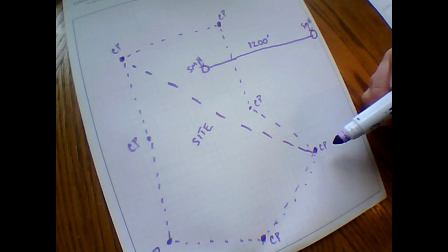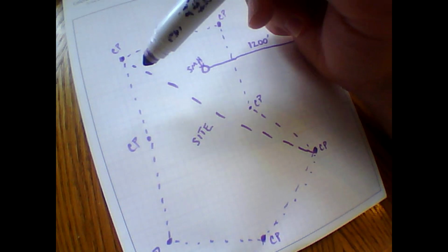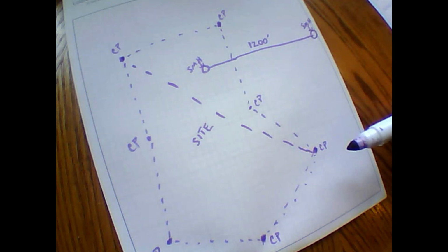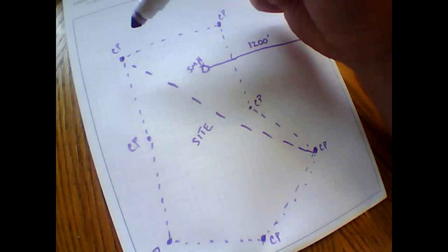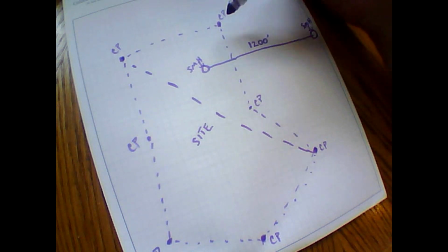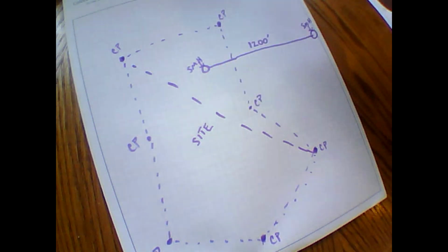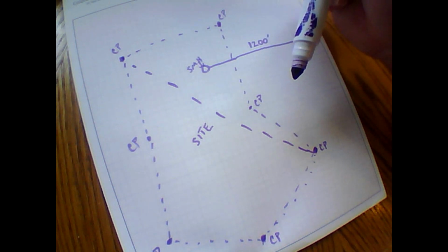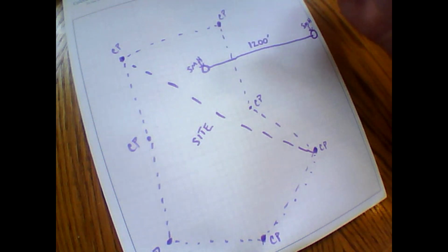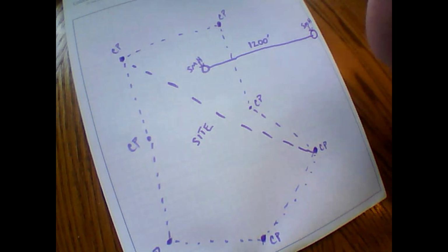Boom, I calibrate to this too. As long as these published values are good values and you don't have any issues with them, this line is going to control my entire calibration. As soon as I do this, I immediately go and tie every other control point and verify that I don't have error, not enough to make it an issue. If you miss it by 300ths, you're going to do that anyway. If this was all set with GPS, that error is already incorporated into your control, so it doesn't matter.